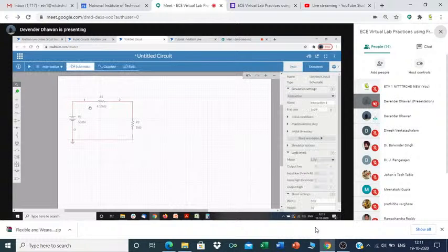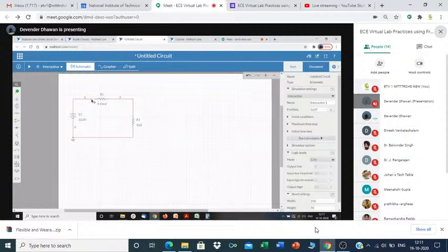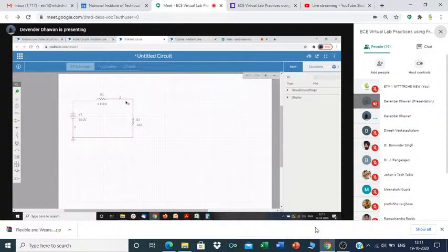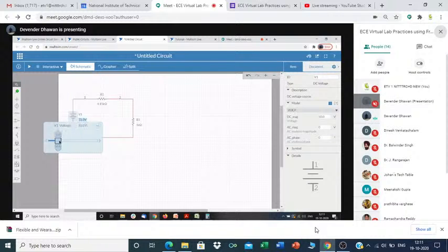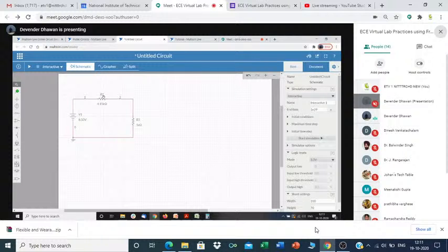So this is our circuit. Okay, then we will just make it, let's say, a little less, 8.5 volts. Now I will apply some voltage probes like here, which will measure the voltage at this point and the ground, which is basically equal to this particular voltage. Now I have to measure voltage across this and this. So the voltage drop across this complete loop should be equal to 0.